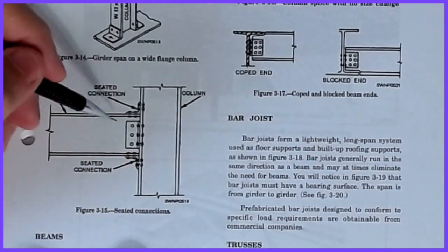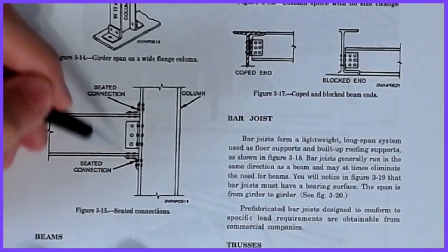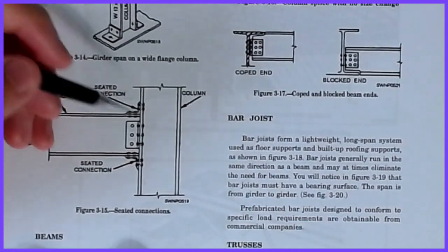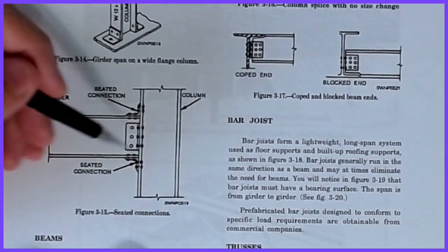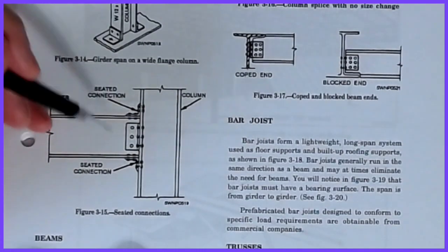And again, a lot of times, on one end of a beam, we'll pre-weld these onto the beam so that you don't have all these loose parts, and then all I do is align the holes on the column, and then we can bolt it in the field. That's one way. So this is a seated connection, if you will. Sometimes you have the tops and the bottom, sometimes you don't, sometimes it's web only. All of these have different behaviors.